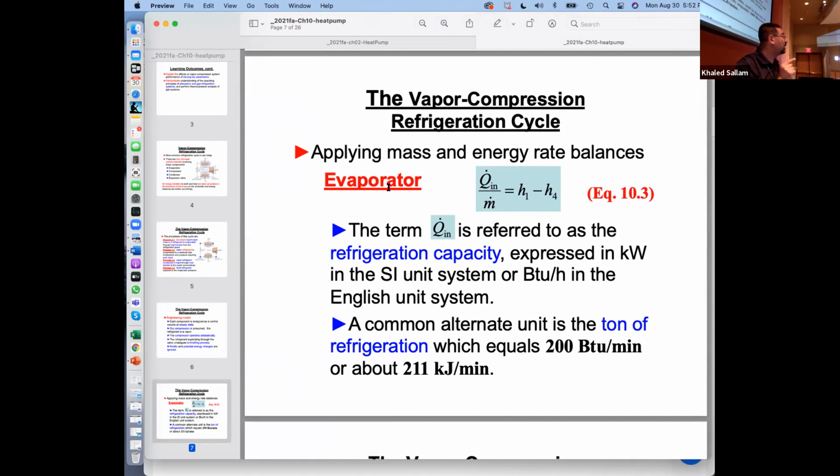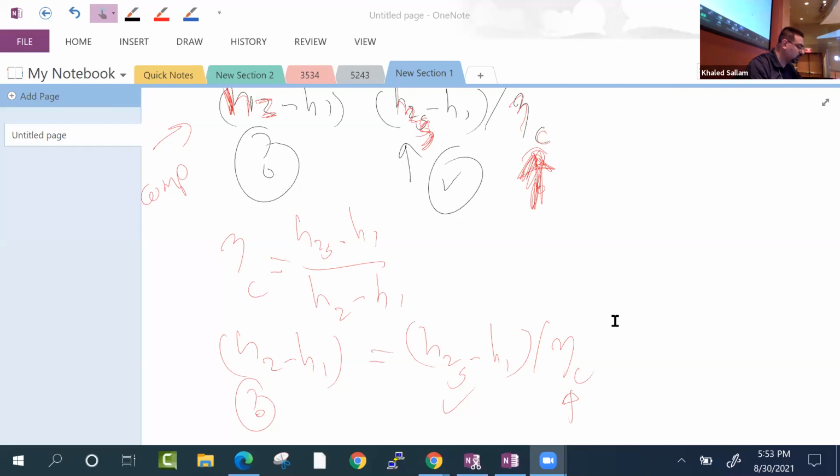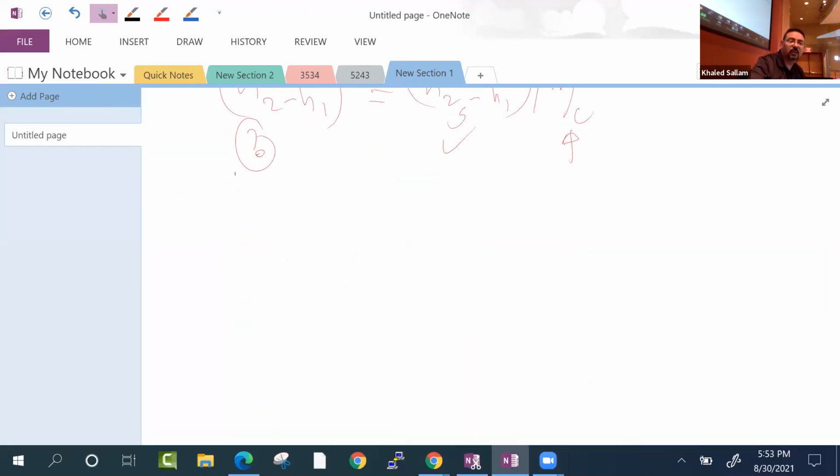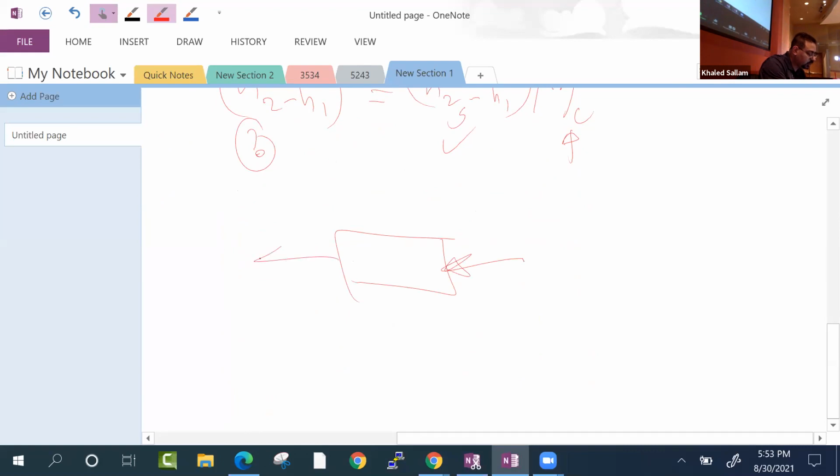And in each one of those, the evaporator, condenser, compressor, just like the Rankine cycle, the first law also has delta kinetic energy and delta potential energy. What happened to those? We neglect them. Why? Because the enthalpy change is just too much. So don't ever forget the first law, because maybe at one point in your own application, it will not be the case, and you really want to harvest that energy, the kinetic and the potential.